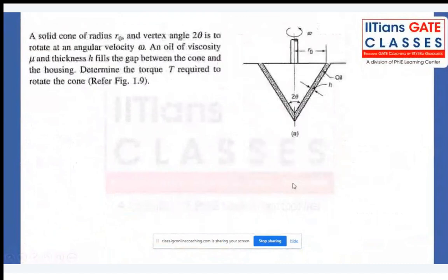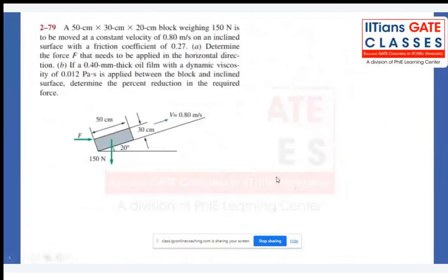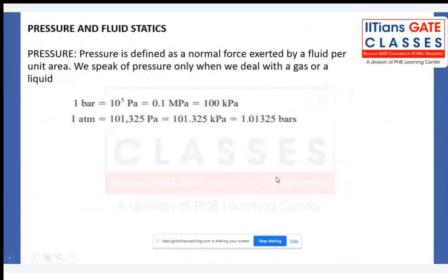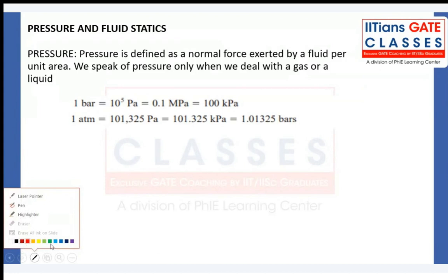Yes. So we are discussing fluid statics, and we have just started our discussion on that. We have seen somewhat the differences between the pressure and the stress: at a particular point the pressure value will be the same in all the directions, right? As it does not have any specific direction, we say that it is a scalar quantity. We also talked about the stress, that stress is a second order tensor, right?